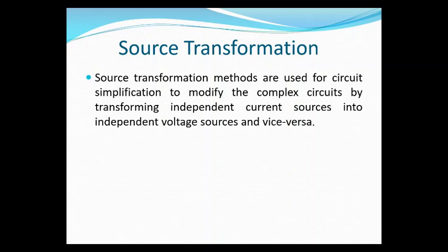What is source transformation? Source transformation methods are used for circuit simplification to modify the complex circuits by transforming independent current sources into independent voltage sources and vice versa. Means the independent voltage sources into independent current sources.